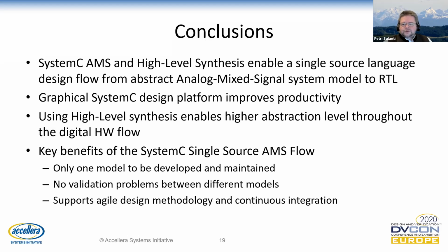With the presented methodology, only one model has to be developed and maintained. No validation between 2 different code bases is needed, and the RTL verification environment can reuse the SystemC test bench. This methodology supports agile and traditional design processes, enabling efficient utilization of the resources.